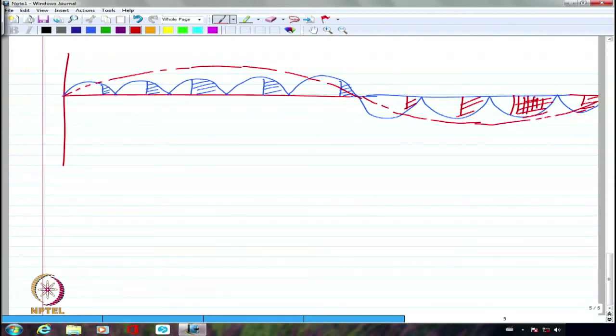So I can control the output voltage approximately to a sinusoid. It is not a perfect sinusoid; it is only an approximation to a sinusoid. So I am calculating the area under the curve, which is normally 3 Vm by pi cos alpha, and then correspondingly I look at not 3 Vm but 2 Vm by pi for single phase. We are talking still about single phase. So I have to calculate for that and then make sure that the firing angle is adjusted accordingly. That will make sure that what I apply as the voltage is somewhat sinusoidal.